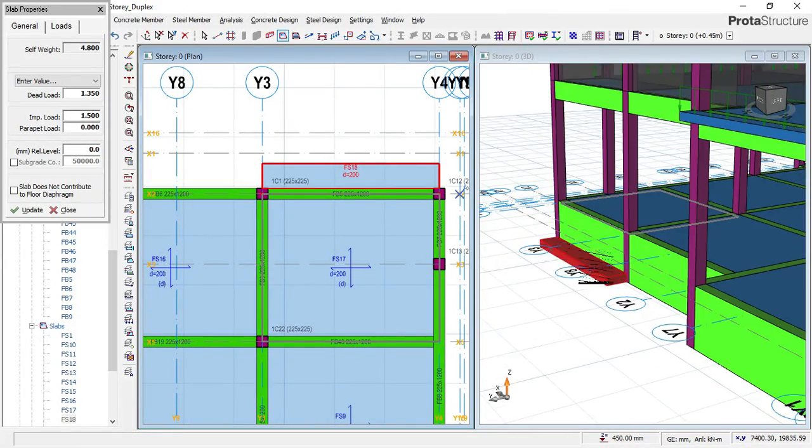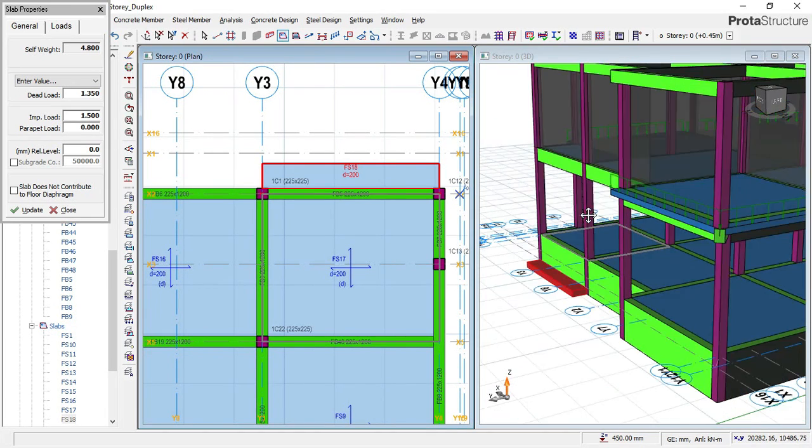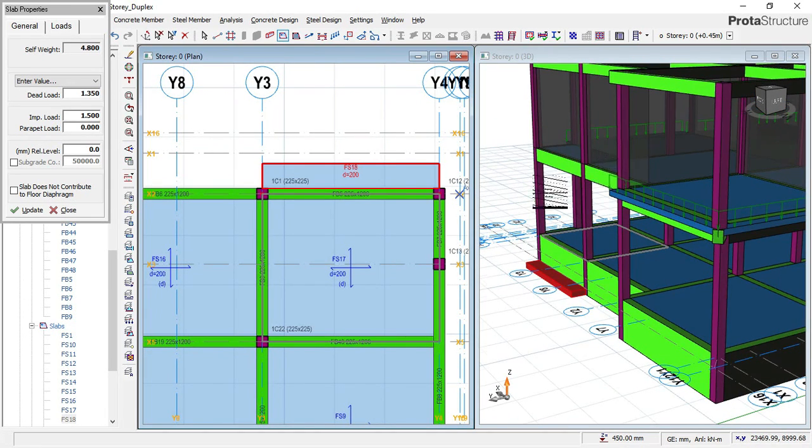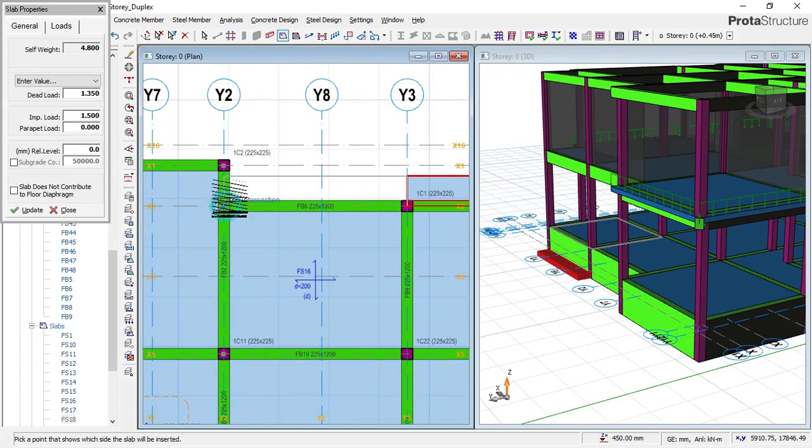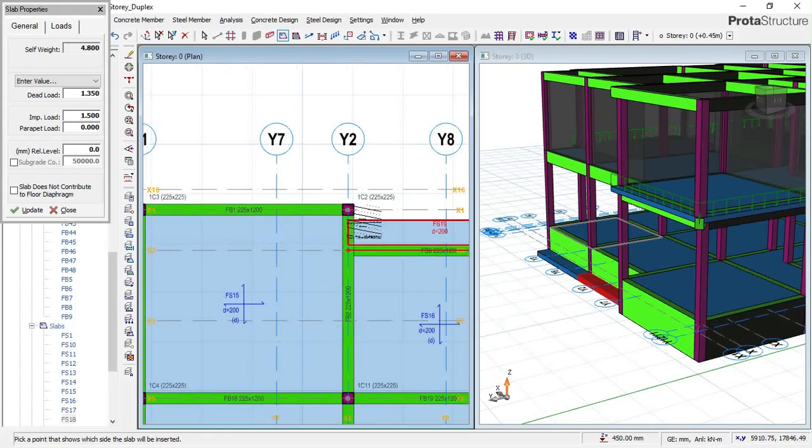So this toe slab, which is the cantilever slab, takes care of the active pressure that is meant to affect this ground beam at the bottom when the soil tends to compress back to its normal shape after displacement that was caused by the weight of this structure. Okay, so right now you have to put your toe on all the areas which have beams. So that's what I'm doing right now.